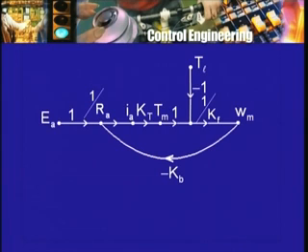So here is the output node omega m, of course, and Kb omega m with a minus sign, so I will put here minus Kb. So this 1 and minus Kb takes care of that difference device. So that is the output here, but that is multiplied by 1 by Ra. So that is the next signal which is identifiable as the armature current,